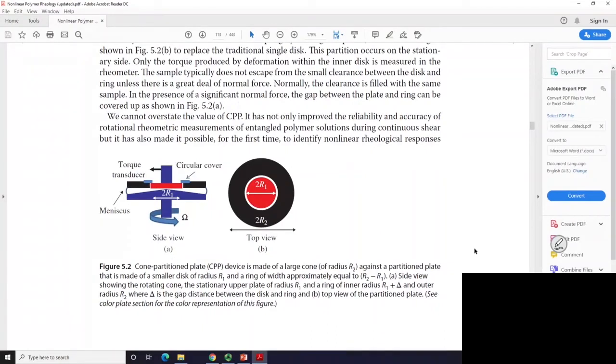You are not only interested in prescribing the deformation field, which is linear, if you pray to God that there is no inhomogeneity, but also you want to make a mechanical measurement. If your edge is going unstable, if your edge here is going unstable, it's going to affect your measurement by definition, because over here, some complicated things happen so that you no longer have simple shear. And this is potentially for all viscoelastic materials. You could, in principle, encounter that problem.